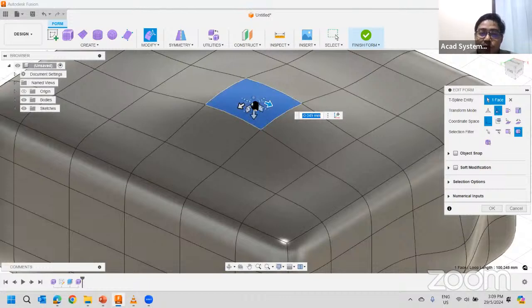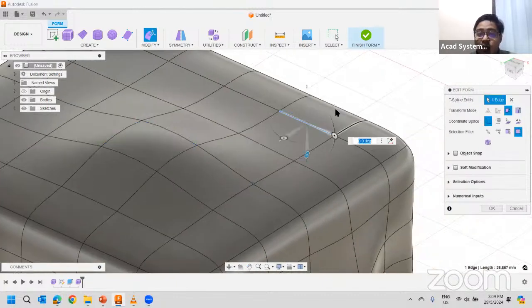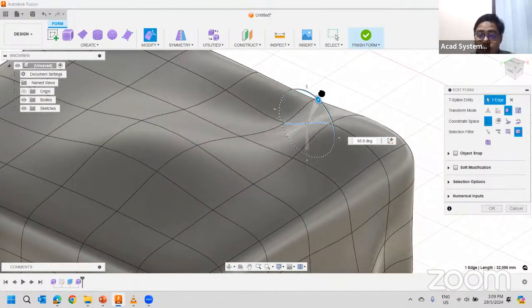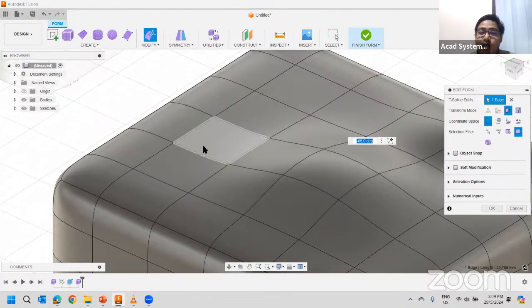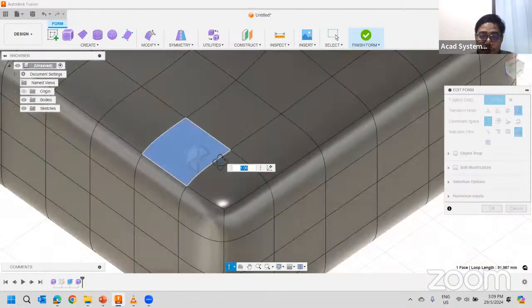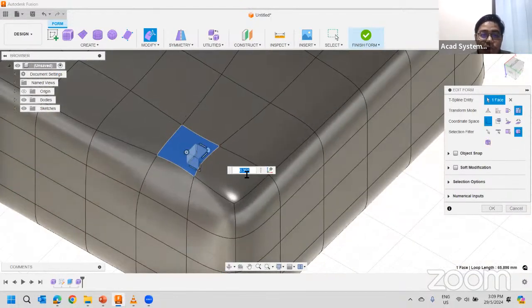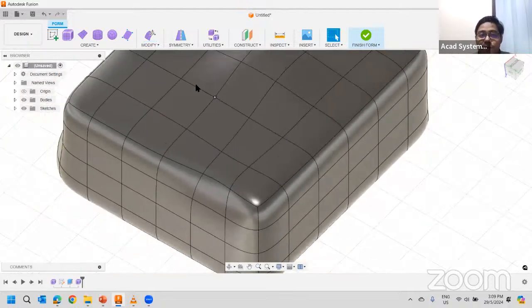Right here, you can also use this plane. If I would like to rotate, I can select rotate. Then it will allow me to rotate only. Or maybe I just want to scale up and down. In that case, I can click the scale factor from here. Again, you can also input the value from here if you would like to. Maybe I make it half of the scale, so I can just input the value as well.